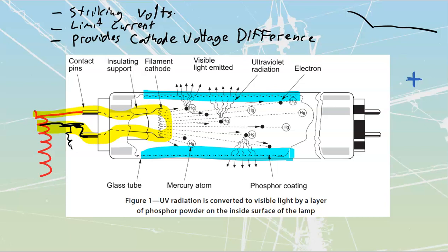Energy efficient lamps have just got improved phosphors. The original phosphors that we had were pretty good, but we have got some improved types of phosphors that are able to pick up and carry that energy longer. Those are going to give you your energy efficient lamps, so we need less current traveling through here, and we're able to convert more of this UV into better visible light.